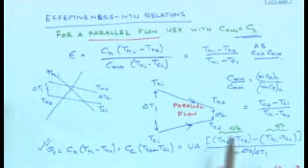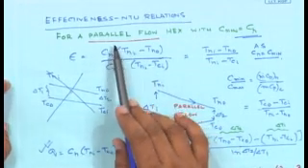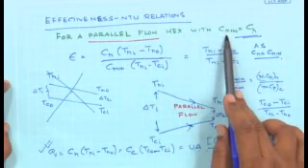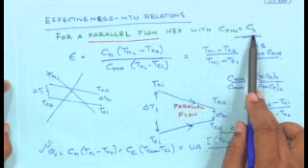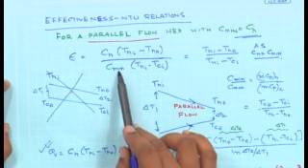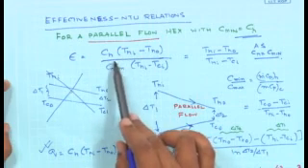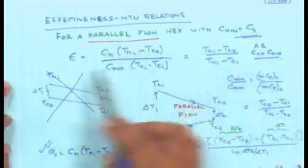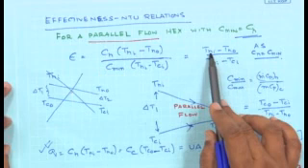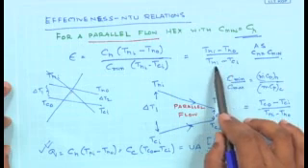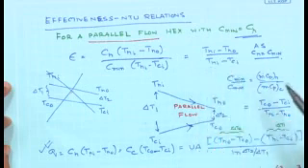So then we went into this effectiveness-NTU relation, and we started to derive the expression for a parallel flow heat exchanger, as I mentioned before, with C minimum equals CH. So CH, which is m dot Cp for the hot fluid, is the lower one. So epsilon would be the total actual heat transferred divided by the maximum heat transfer that could take place, and in this case C minimum is simply equal to CH. So CH would cancel from the numerator and the denominator. So your epsilon should simply be the temperature change of the hot fluid divided by the maximum change that can take place in a heat exchanger of infinite length. So it's Thi minus Tci.